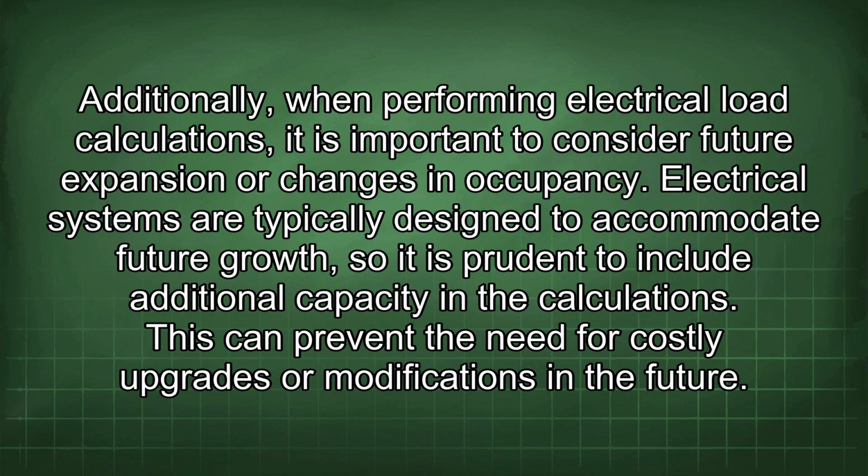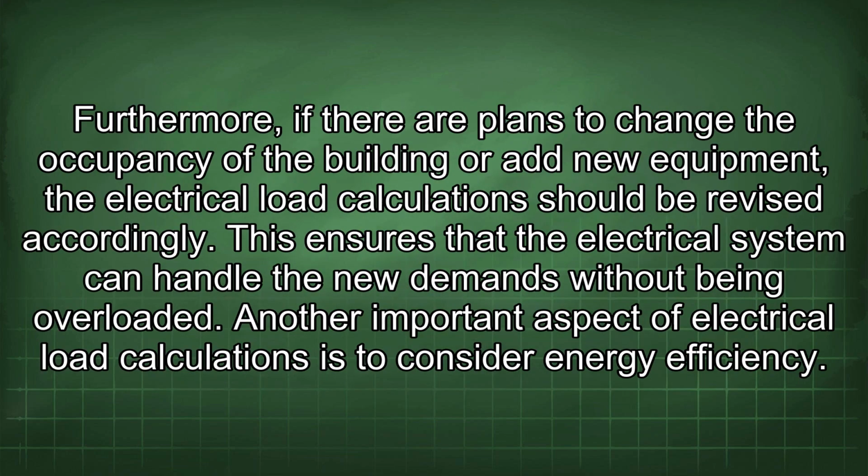Additionally, when performing electrical load calculations, it is important to consider future expansion or changes in occupancy. Electrical systems are typically designed to accommodate future growth, so it is prudent to include additional capacity in the calculations. This can prevent the need for costly upgrades or modifications in the future. Furthermore, if there are plans to change the occupancy of the building or add new equipment, the electrical load calculation should be revised accordingly. This ensures that the electrical system can handle the new demands without being overloaded.